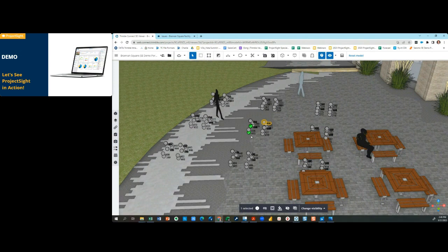What you're also seeing is some point layout. These green check marks visually show which points you've laid out. I've got a SketchUp model in the background just to give us some points of reference. But green's laid out, gray's not done yet. And if you saw a red X, that means the layout's out of tolerance and probably needs some attention.